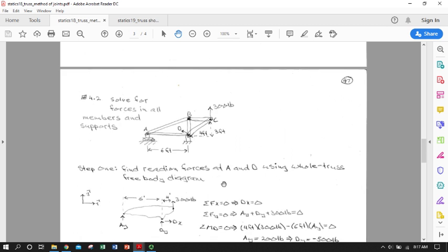So this is the last of our method of joints examples. Basically, they're all the same. You do them all the same way, even if you're doing a space truss. You just add one more dimension. You will only have moment equations, as part of your equations of equilibrium, in the overall truss FBD, the whole truss FBD, where you're solving for your support reactions.